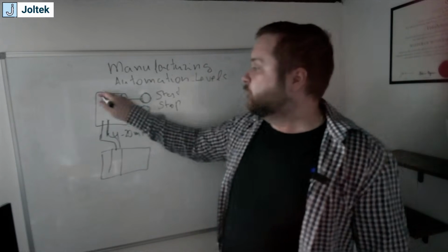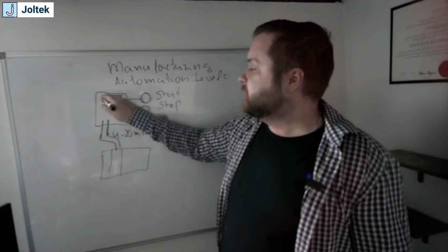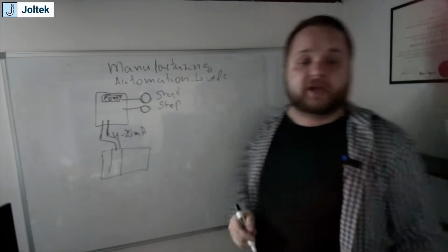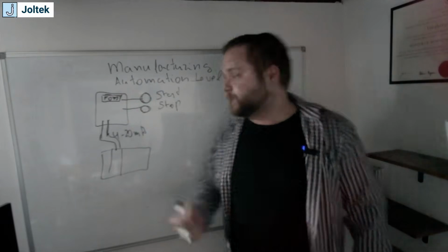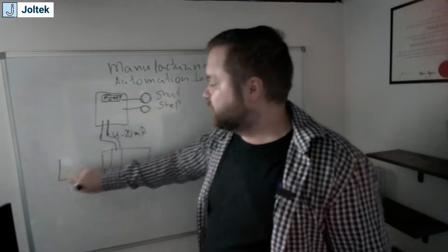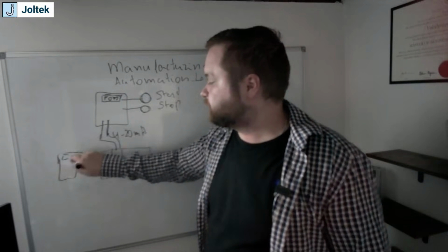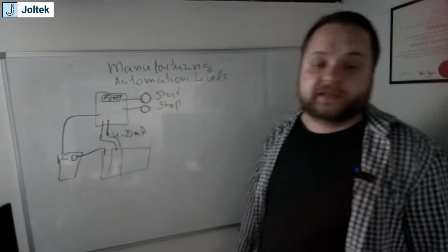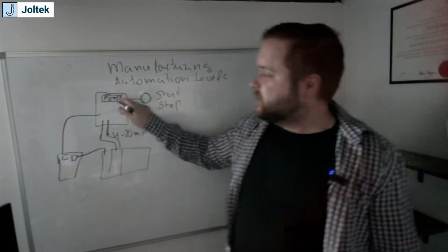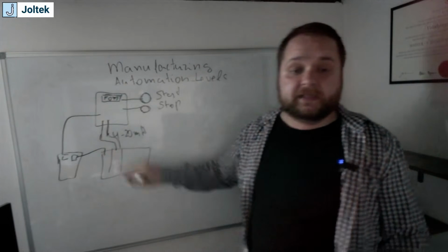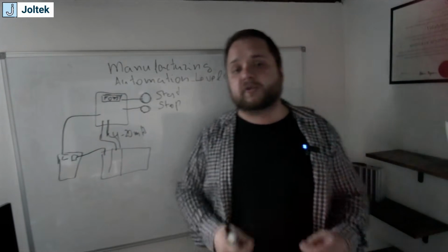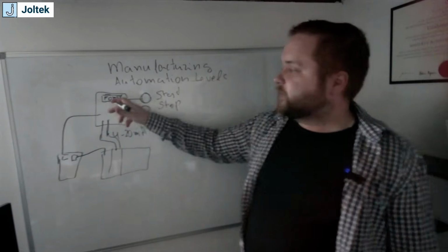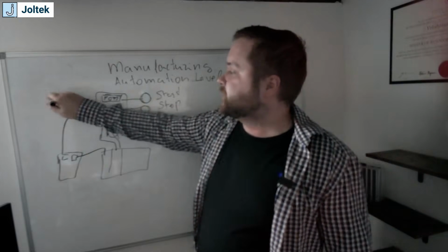So if I'm looking at a VFD, I'm going to have this little screen, and this is going to say, for example, fault 073, and then I can look in the manual and understand what that issue is. If I connect over Ethernet, and I'm going to redraw again, this is going to be a switch. So imagine that my VFD is connected over Ethernet, and this Ethernet cable is connected to my PLC. I can now get this error into my PLC and I can react accordingly, but I can also troubleshoot and display that either on the HMI or the SCADA screen. So I could see, for example, that F73 is torque overload.